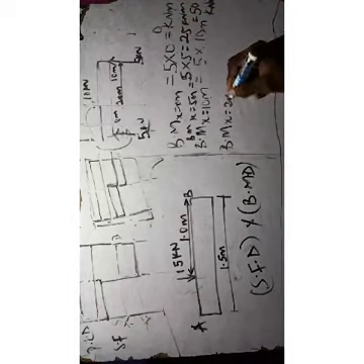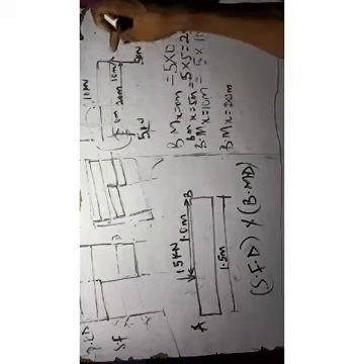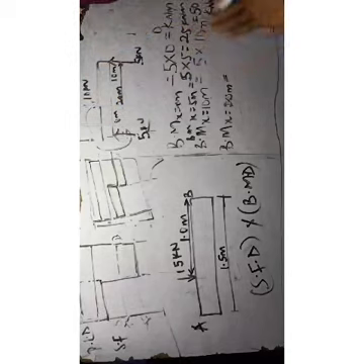So you can also do it for x equals 20 meter. Don't forget, only for simply supported beams can you jump like this. Do not do it section by section. If it were to be UDL, I repeat, you do it line by line. You take the distances to be equal. And if it were to be VDL, you take the distances to be equal. So bending moment when x equals 20 meter, you will have at this edge here, right? That is 0, 10, 20. At this 20 meter it will also be 0, I told you, right? So you can take the distance as well.